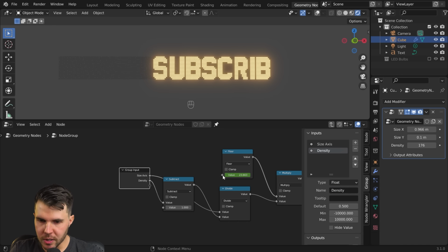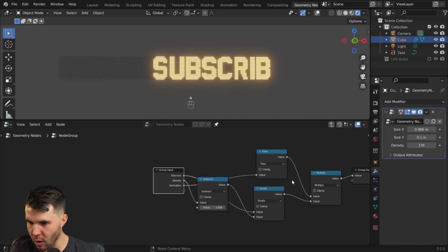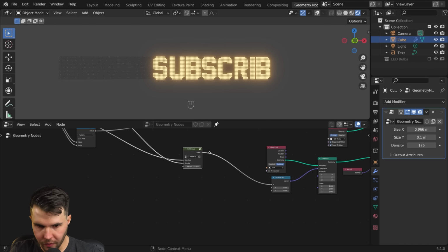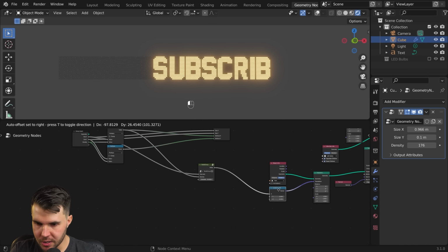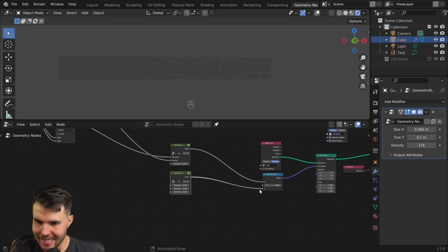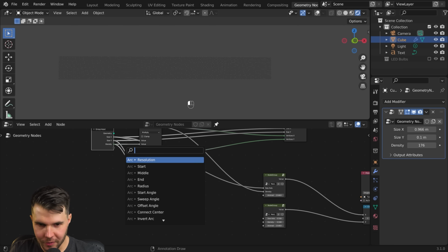And then I also want to expose my animation value. So let's put this here. I've now lost my keyframe for that because it's now exposed and it's overriding the value, but that's all right. And now, if I want to create the exact same system for the X, I don't have to duplicate and do a bunch of stuff. I'm just duplicating the node group and putting this into the Z axis, and then make sure I connect. I have to do this correctly.